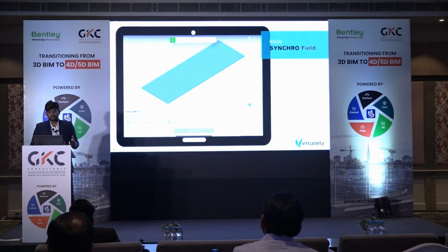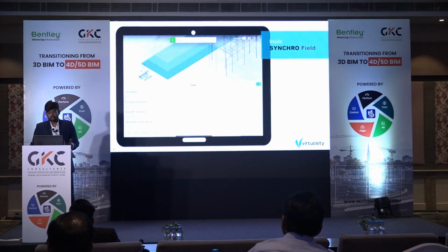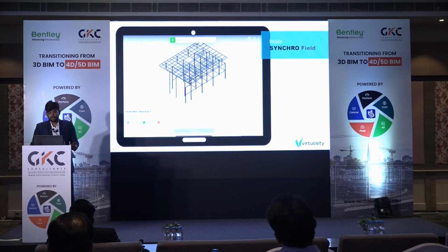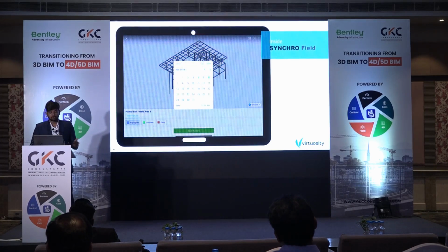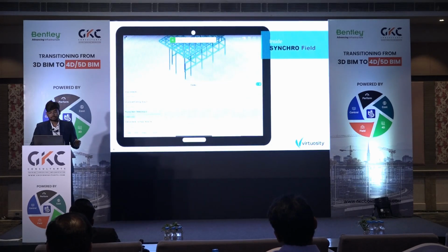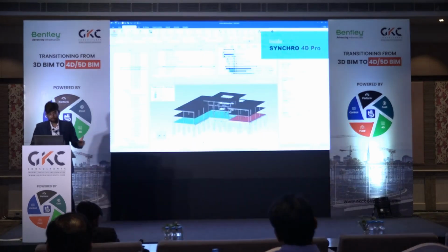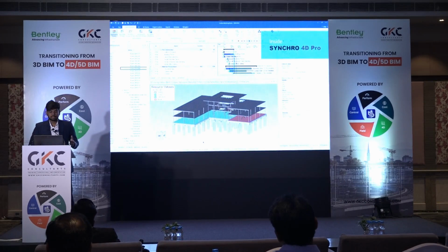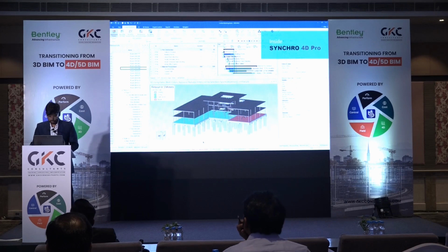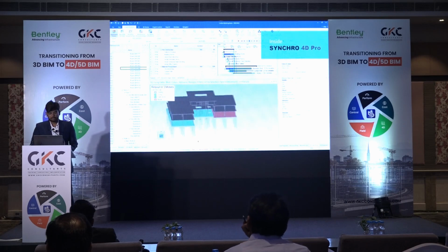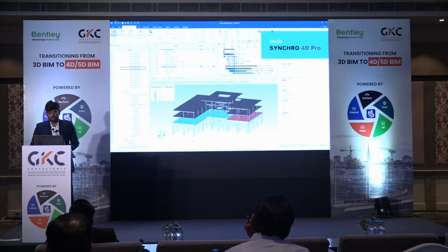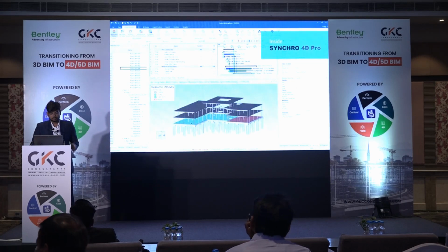And when we update this information from the site, the whole thing gets synced back in your Synchro4D Pro main model. So here is another piece of information. We say that the tasks which were in progress are now complete. We select a resource and we update the information. And now inside Synchro4D Pro, this information gets synced back through the cloud connection. Here you would see color-coded information which says what the different stages of the parts are.